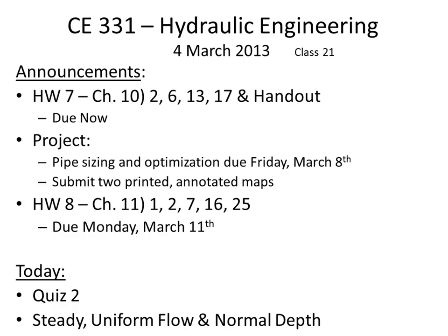I've got a question about what elevations should be used for the junctions. It's okay to use just the ground elevation for the junction, or if you'd like, you can assume that each of the junctions is buried the same depth underneath the surface. So maybe if you find the elevation of each of the junctions, then you could say that the junction itself is buried 2 meters lower than that. You know, either approach is fine.